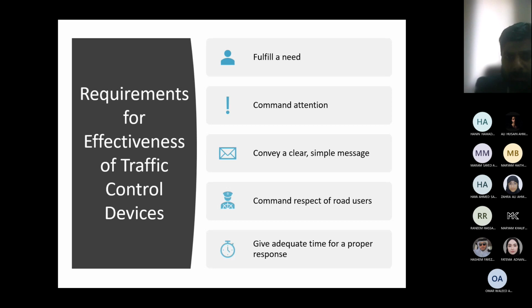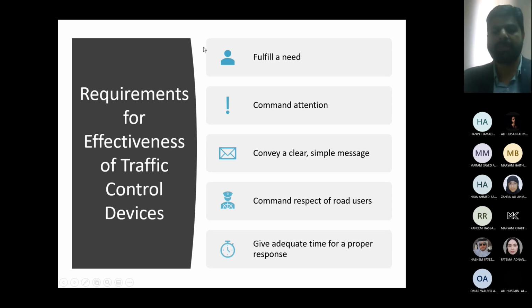Signal is not a small thing. A roundabout, again, is a very prominent structure on the road in the middle. You will see it. But the point from where you will see the signal on the roundabout may not be enough for you to do something to stop properly. Maybe the geometry of the road is such that you will see the signal when you are 50 meters in advance, and 50 meters may not be enough for you to stop. So they provide an extra sign there. Again, the purpose is that the driver should be able to do the proper response in proper time.